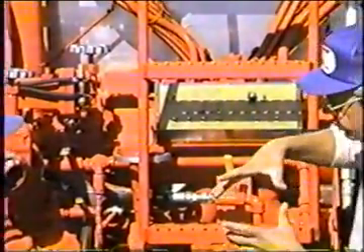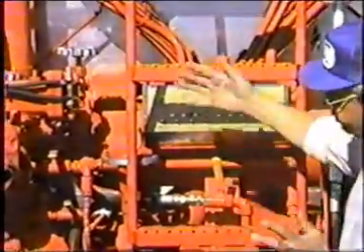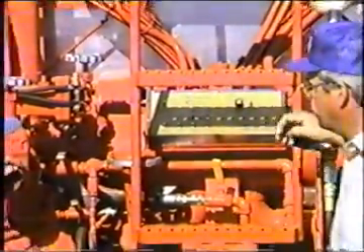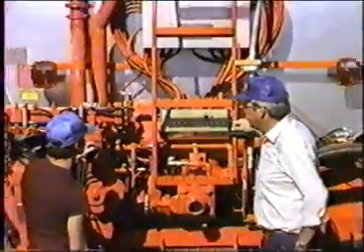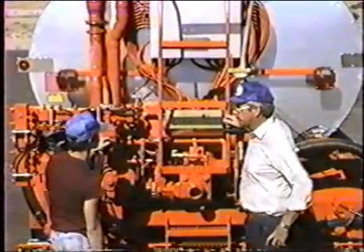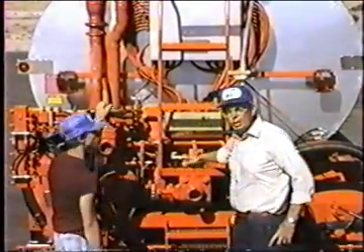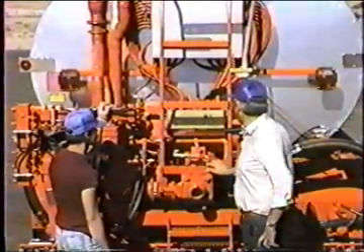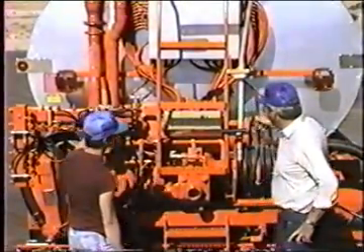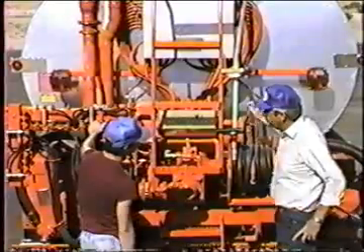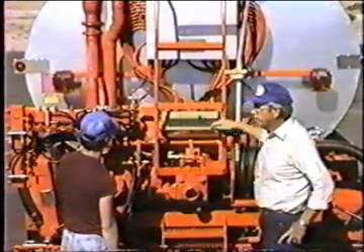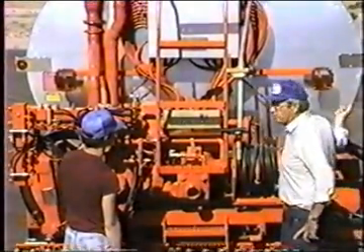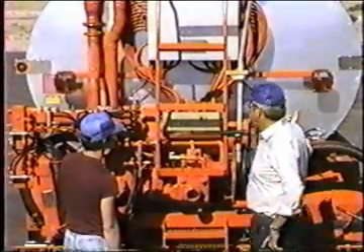That's a big conical screen that's 6 inches in diameter and about 30 inches long. Has a lot of screen area, and it has 1/8-inch size holes in it, so it catches some material that could get through this screen. Now it will get caught in the fine strainer. Again, it's easy to clean. The 4 lugs on the end, of course you close all the valves ahead of it, 4 lugs on it, and the screen basket pulls out.